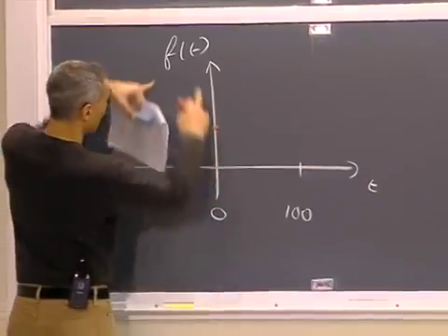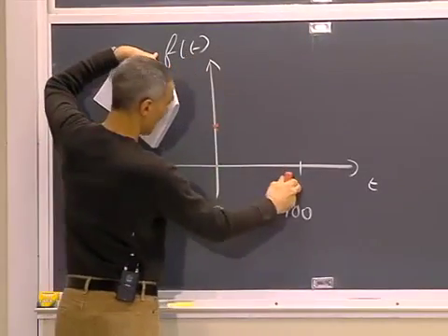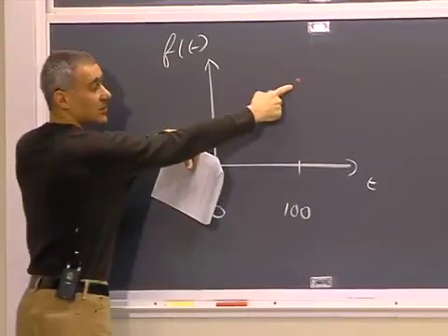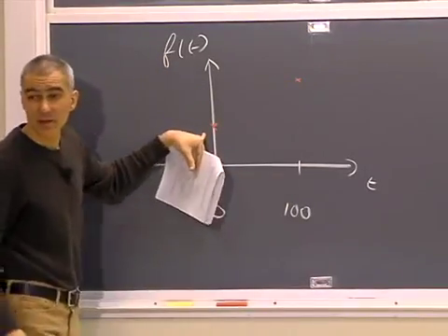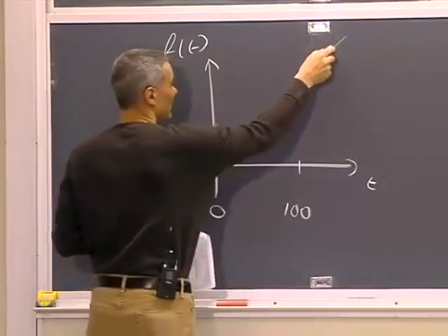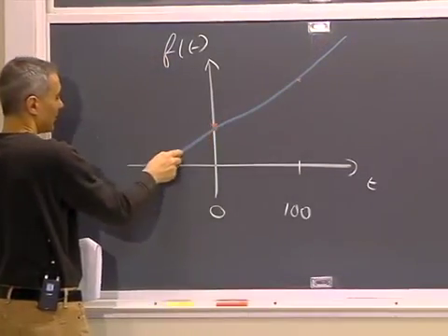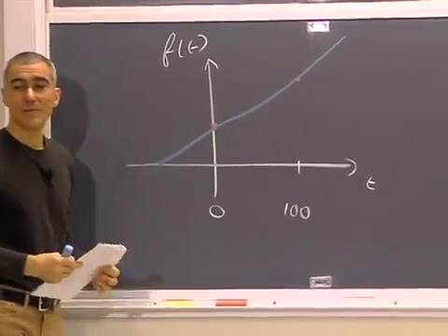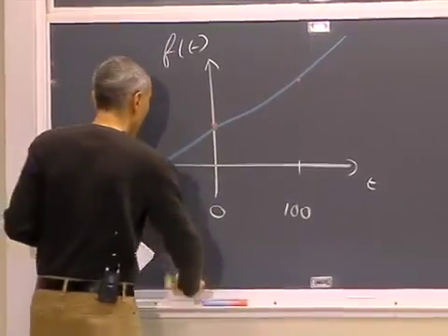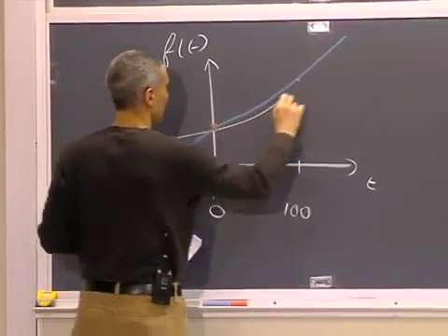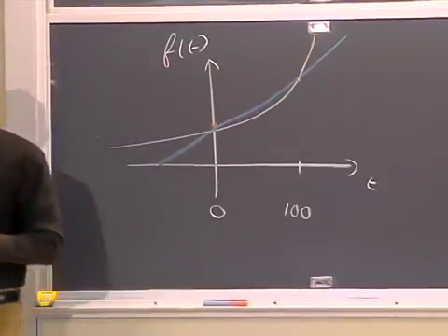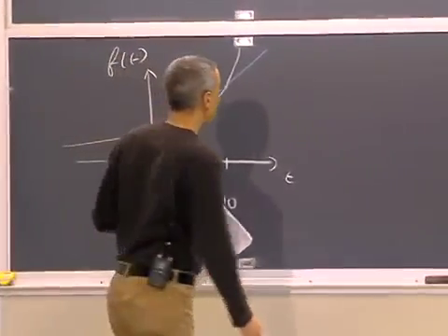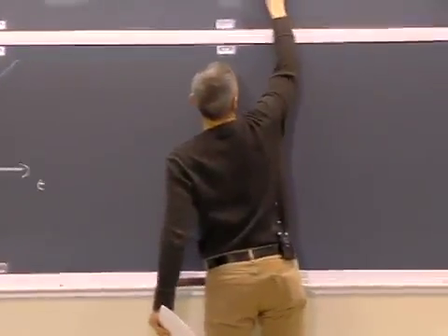There's another value connected to this property when t is equal to 100, our reference point here. Now, there are many ways I can connect these two points together. The simplest way is to draw a straight line. It's called a linear interpolation. My line's not so straight right here. You could do a different kind of line. You could do a quadratic, let's say, something like this. That would be a perfectly fine interpolation. We choose to have a linear interpolation.